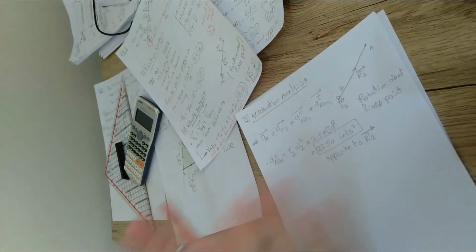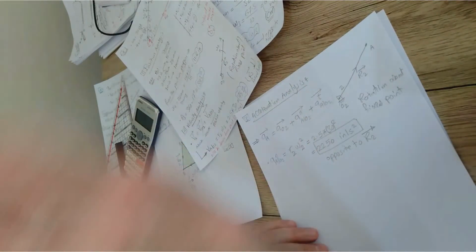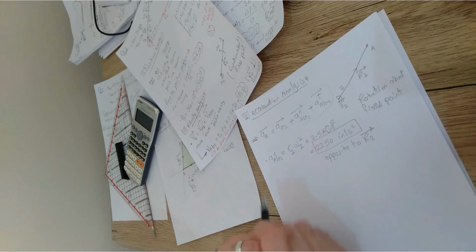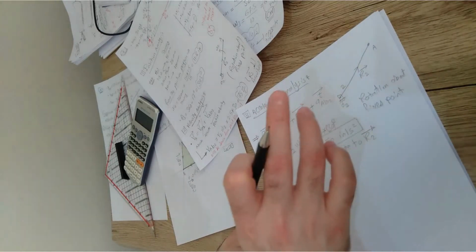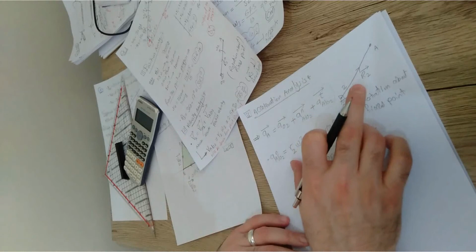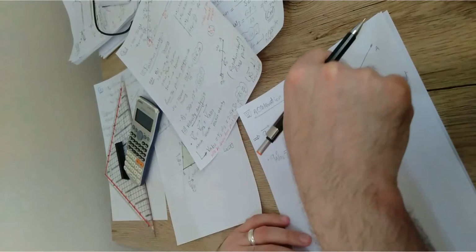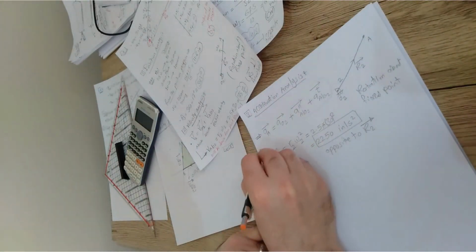But for now, we do have a length that rotates about a fixed point, and this is a straight length. So in this case, definitely the A2 relative to O2 normal will be R omega square, and it will be all the time known. It cannot be unknown, and all the time it is opposite to the R of the same length that you're already considering, which is length 2. Make sense? This is the first component that shall be drawn.